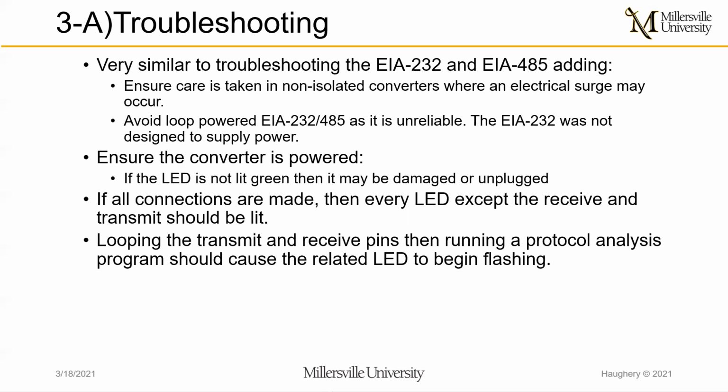Ensure the converter is powered. If it is not, the LED will not be lit green and may indicate that the unit is damaged or unplugged. If all connections are made, then every LED except for the receive and transmit should be lit. Connecting these two together and then running a protocol analysis program should cause the two related LEDs to begin flashing.